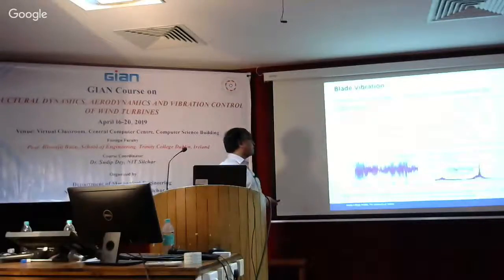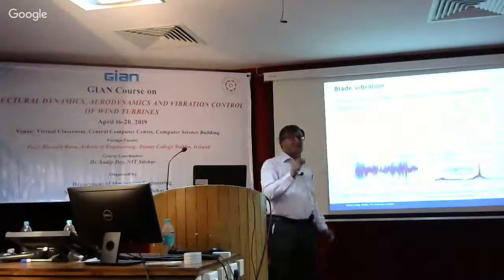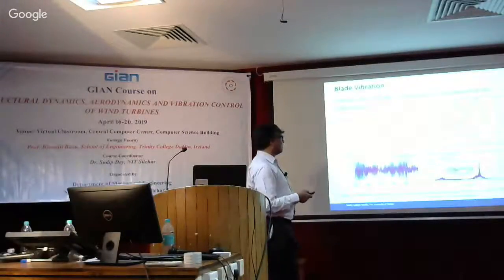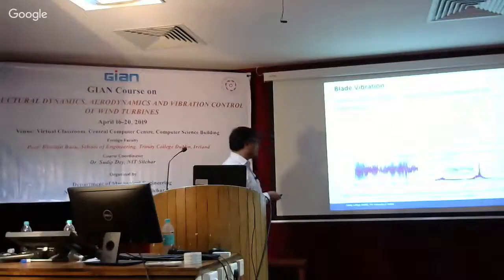So passive vibration control gives very encouraging results, and you can see that this is the orifice ratio. If you vary the orifice ratio, like using semi-active means, you can control the amount of damping and optimize it according to the speed of rotation as well. Here we can see that with and without TLCD, we have a significant reduction in the response. This is without, and this is with the TLCD.